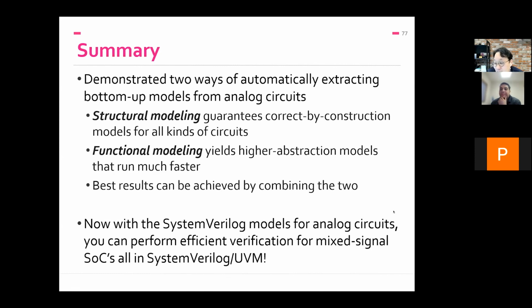These are all troublesome when you try to model them in a signal-flow model. I assume Saurabh is coming from experience with the real number model, where to address that, they introduced what's called a user-defined net and a resolution function to determine the output when there are multiple things driving a single node. You don't have to do any of that. If you have multiple voltage sources merging into one through some resistors, then it will be determined by those impedance ratios and so on.